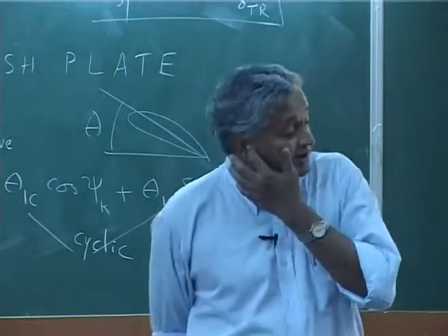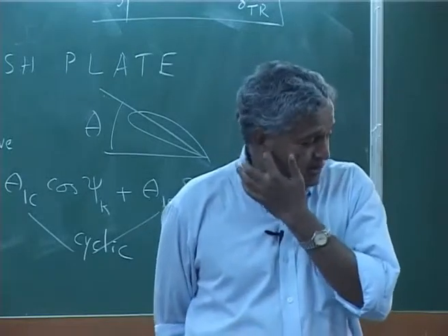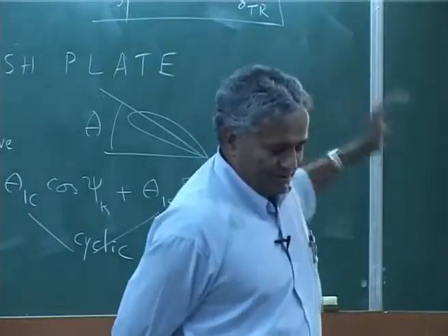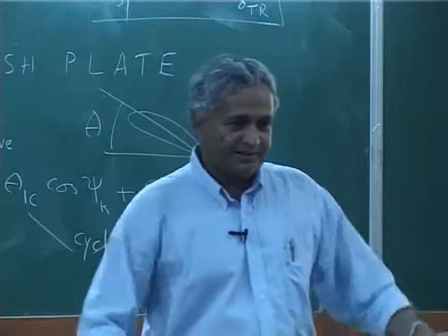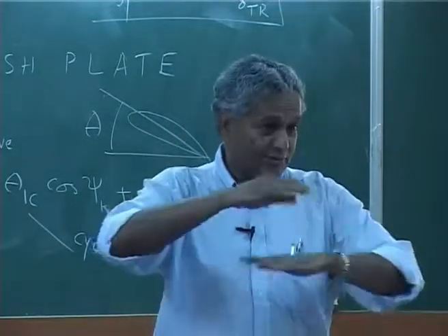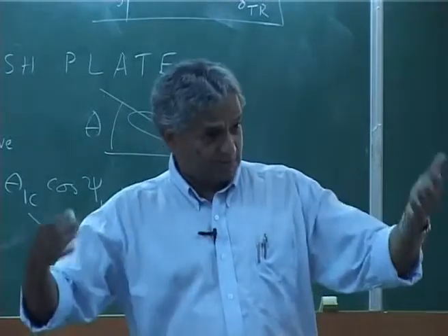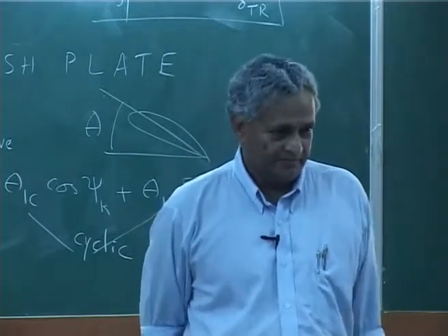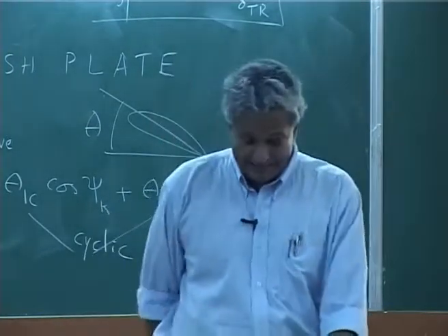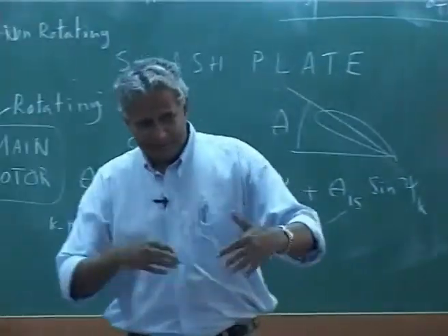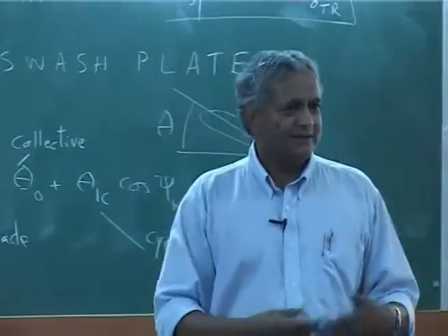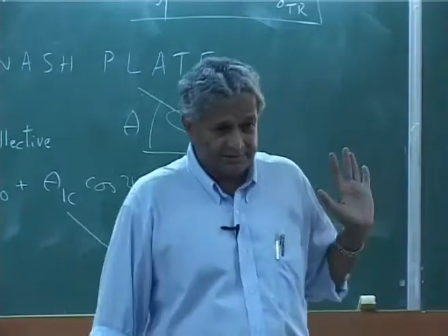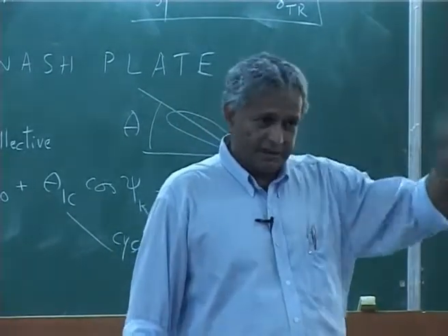The US started this a long time back, Sikorsky, but of course they had a lot of problems, because they thought as we go along the program we will learn the advantage. They thought I can get the advantage from both the rotors, but actually the disadvantage also comes from both the rotors. So, what they thought they could achieve, they could not achieve, and the project was abandoned. But again I saw just about last week in the newspaper, they made this helicopter again, maybe they are trying to do it again. They call it advancing blade concept, but it is nothing but contra rotating rotors, which the Russian Kamov has.